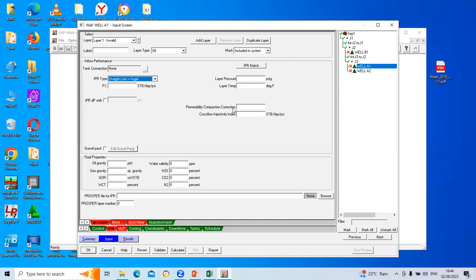So as you're drawing, the pressure is reducing, the pore spaces are also compressing. Why are these pore spaces compressing? Because the grains are expanding. The grains of the sandstone or whatever we have there are expanding due to that drop in pressure. As the grains are expanding, they are squeezing the pore spaces.